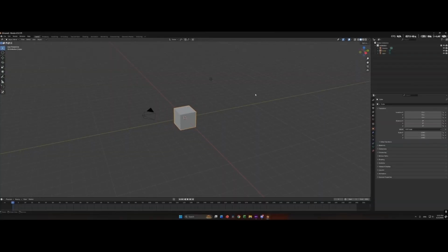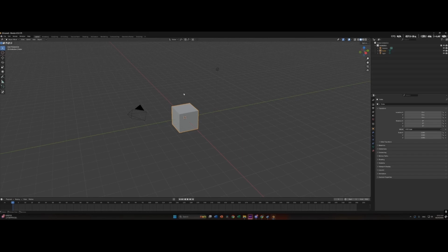All right. So for this part, I'm going to teach y'all how to pan. Panning is actually very easy in Blender. It's quite simple. You only have to press Shift plus the middle scroll button. Now look, you're panning away from the object. Yeah, it's so cool, right? So why not give it a try?